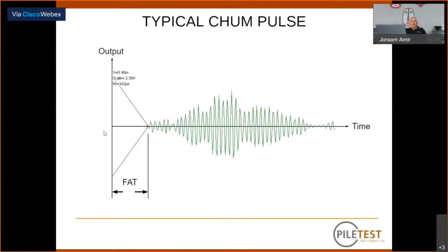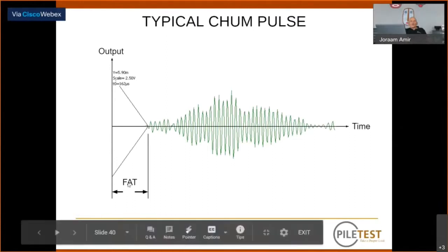Now we said we have an emitter or transmitter sending the ultrasonic pulses, and this is what the receiver is getting. This is the time base. Here, the emitter is producing the pulse. While it's traveling, the receiver is stationary. And then it starts getting the waves arriving. The first arrival time, or in short, FAT, is recorded by the system automatically.